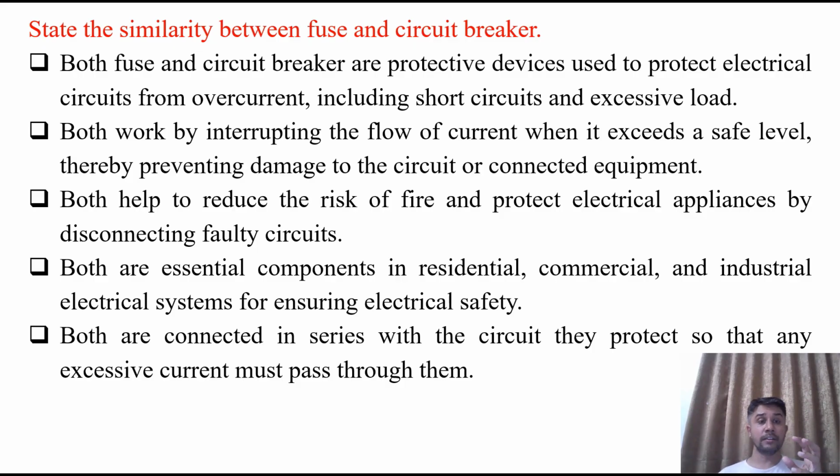The main point of similarity between these two devices is the type of connection. Both are connected in series with the circuit, so that any excessive current must pass through it. So these are some points of similarity between fuse and circuit breaker.